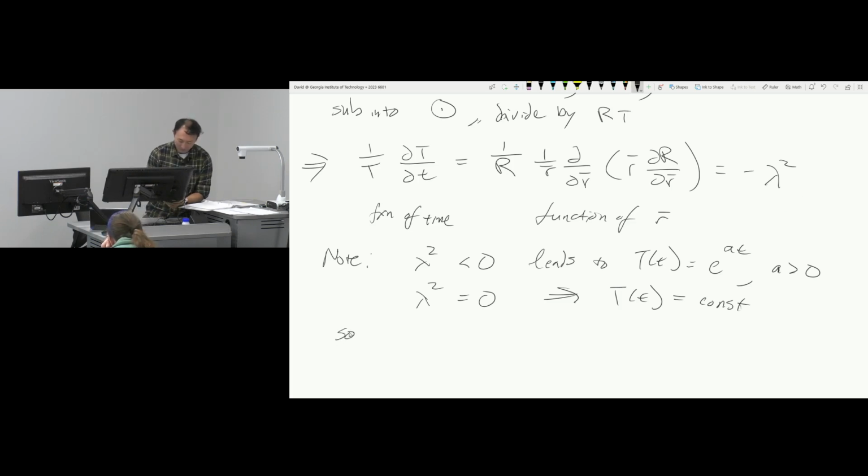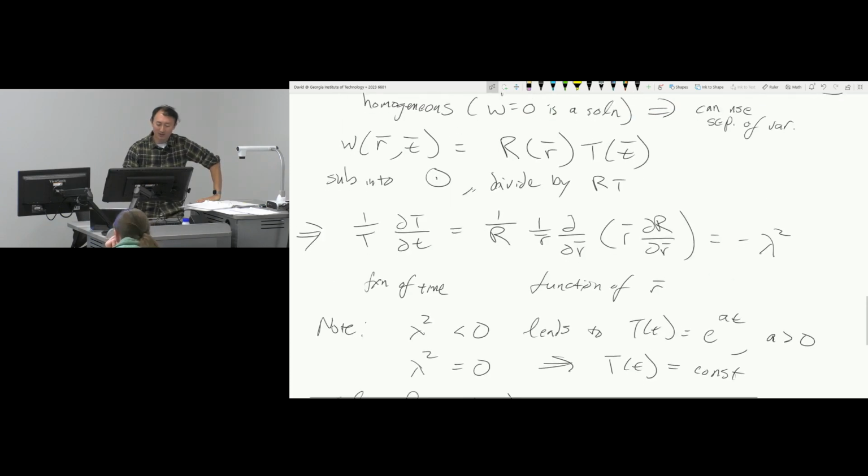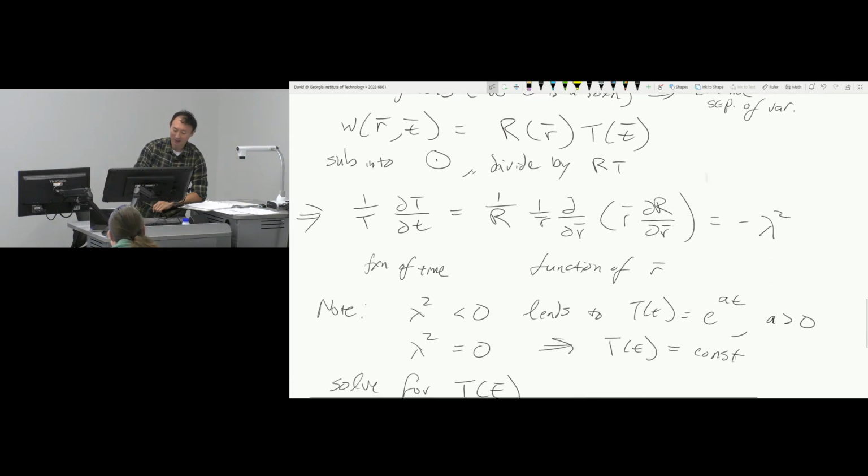All right, now here's the issue. Separation of variables has led us to make progress. The roadmap is: we start with a dimensional PDE, we make it a dimensionless PDE, then we come up with two solutions, a steady state solution and a transient solution. If I substitute the steady state solution, I get a homogeneous PDE. Now I've said my transient solution is a product of these two things, and I get ODEs that I can solve. Each of these ODEs has a constant on the right.